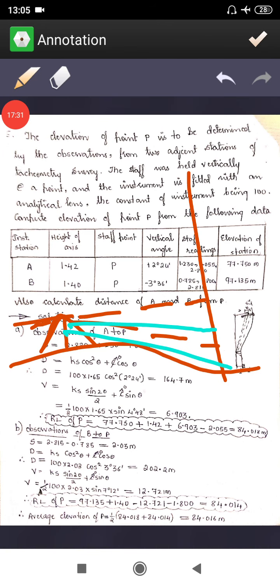Now if you see this figure, what I am going to have, this is RL of ground plus H. If you come here, then this is the RL of instrument axis. Now what is your V? V is, see this dotted line, this dotted line means line of inclined instrument axis to the line of collimation. This is your V. So here you come here, minus V you come here, then this is your H. H is here, so that you have to deduct there. So that is what I have written here.